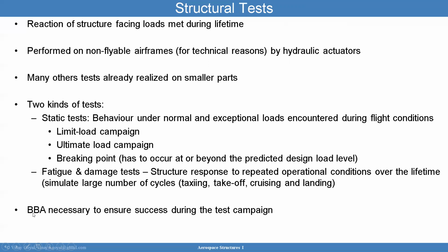And like I said many times before, the building block approach is necessary to ensure success during the test campaign. Here we're looking at small coupon level tests, subcomponent level tests, and larger component tests, all the way to the full scale test. And what we want to make sure is the analysis can match the testing at every step of the way to increase the confidence in the design.